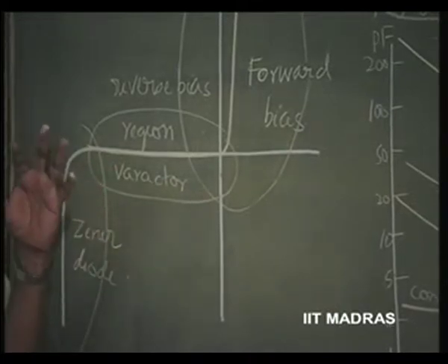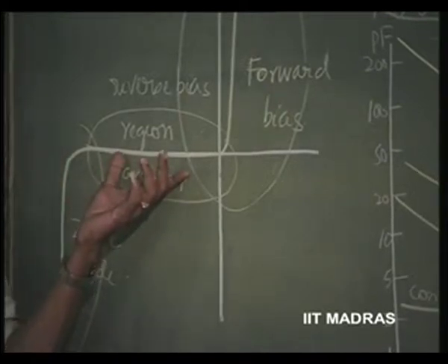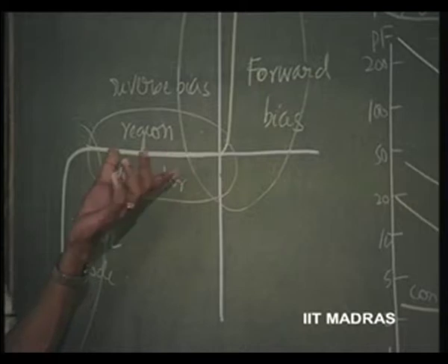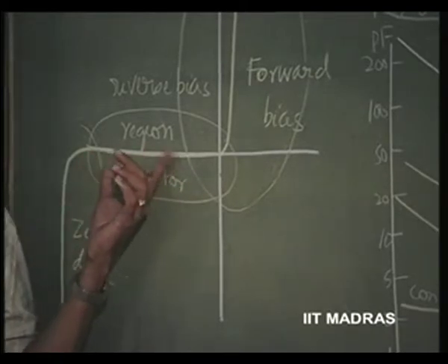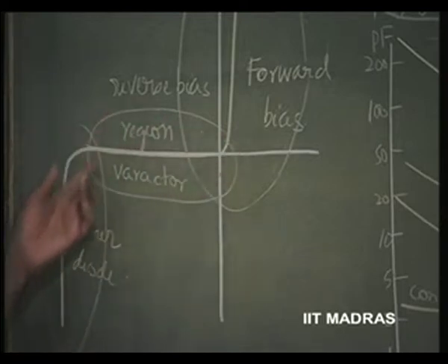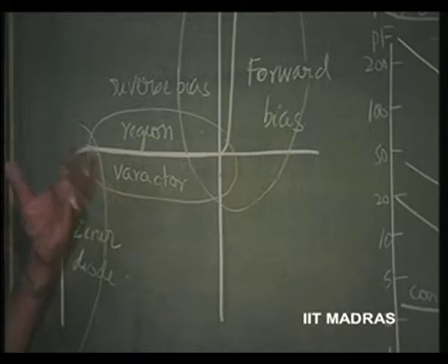But therefore, you have to remember that power diodes sometimes should not be really used for high speed applications, because the capacitance of it is really very high. So, that means for high frequency rectification, you should not use conventional power diodes which are used for 50 hertz. This is the normal confusion that exists.